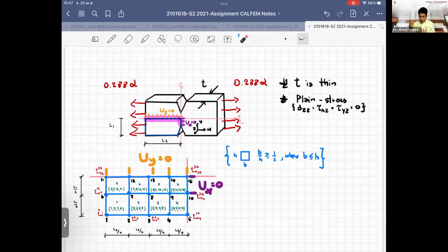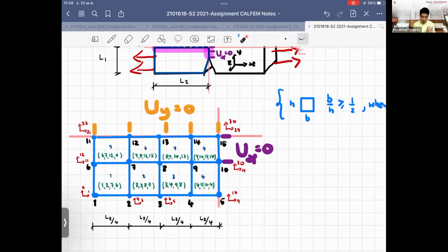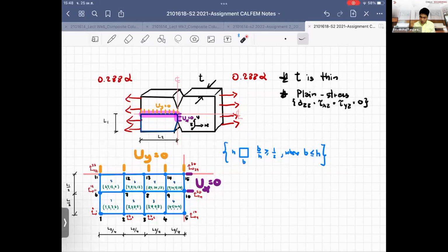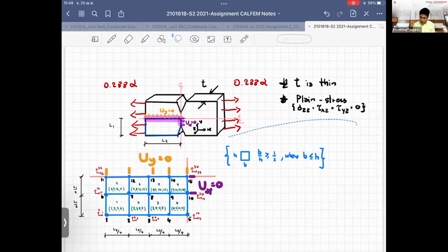And let me talk about the concept of when we have the information of the stress at the Gauss point. When you solve the problem, the stress value that you have corresponds to the Gauss point, and the strain value that you have corresponds to the Gauss point as well. When we solve for the stress at the Gauss point, what it really means is this. Because we use numerical integration, let me move this to the corner.